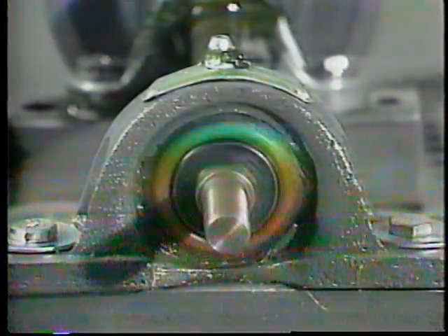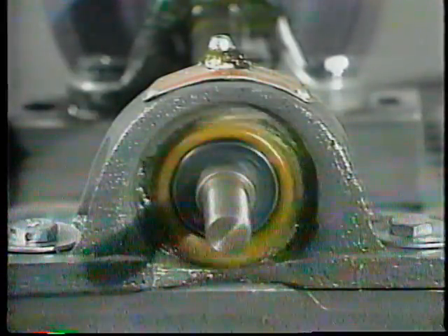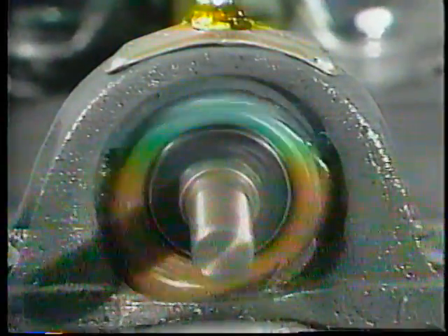Sometimes the stiffness of grease can change, even if temperature remains the same. For example, stiffness may change if different greases are mixed together, and some poor quality greases will become more fluid if worked or churned vigorously. When this happens, the grease may permanently change and may no longer be suitable for the application.